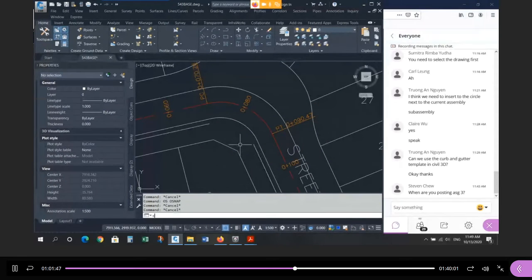Use your intersection O-snap, and you use it in two parts. Okay, I'm going to draw a circle where the intersection of these two lines is. See how if I click here, it's just an X? The little marker is just an X. Well, the actual location where those two lines intersect is not actually shown. Instead of picking one location and drawing from an intersection, I can pick one line. I can click here, intersection.